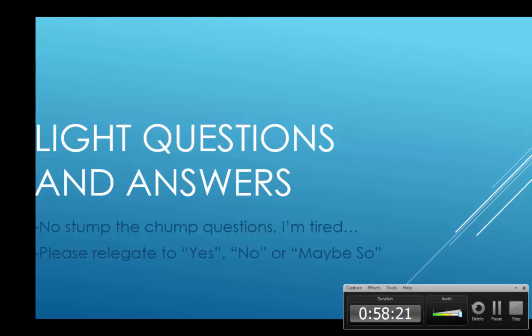So if you're trying to control the length of a sketch in a part, you need to have a configuration in the part that we can now call to. So if you have two different sizes of a part, you don't control that size at the assembly, you control what configuration of that part you're going to look at in the assembly. So that's usually one of the biggest things we run into.